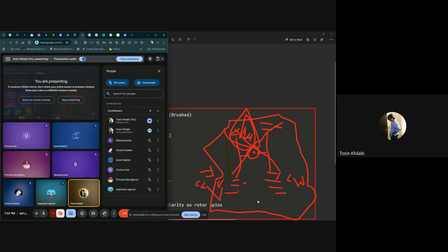Now you might be wondering, what is motor back EMF? What that means is when the motor stops, it acts like a generator briefly. It reverses, and what it does is produce a voltage spike. That voltage spike is what we call back EMF.